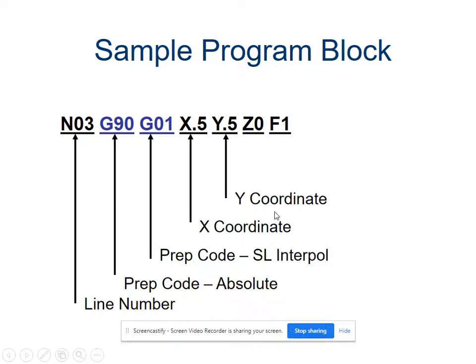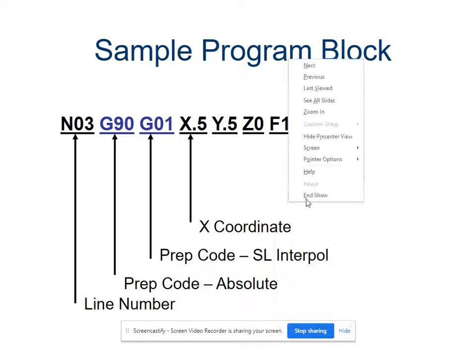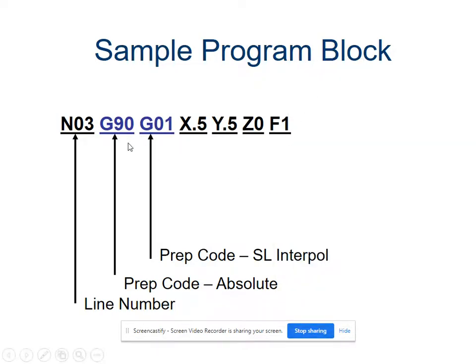Oh, I should go back here and say something. When you give the program commands, gosh, what's the word for it? I just had it a second ago. What it does is it remembers the command, all right? So a G90 is maintained by the program. You don't have to, on every line of code, type in G90 space G01 unless you're not doing a straight line, okay?